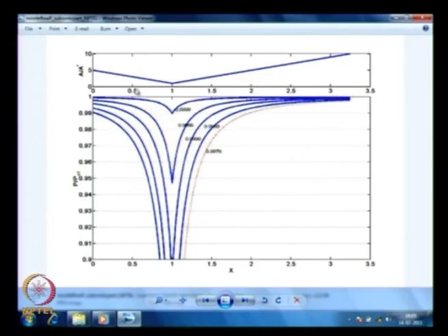Even if I stretch this nozzle along the x axis, the flow will not change, except the plots will also be stretched along the x axis. That does not mean anything for us, we will not worry about it for now. Now, if I look at the Pb by P0 value, I have to show you what the plot is. It is pressure normalized by P01, that is the initial stagnation condition somewhere far outside. And from there we are plotting for different locations, as if I am having pressure measurement all along this nozzle. That is what I am plotting here.